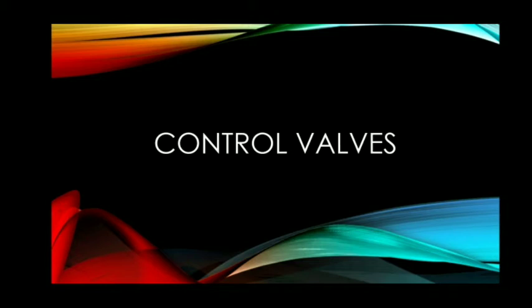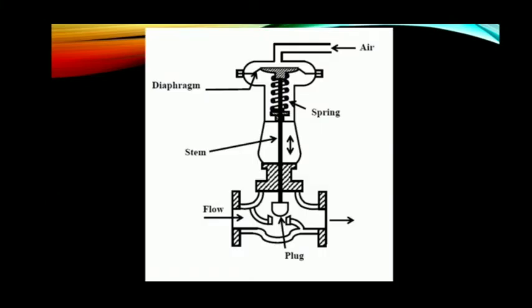The control action in any control loop system is executed by the final control element. The most common type of final control element used in chemical and other process control is the control valve. A control valve is normally driven by a diaphragm-type pneumatic actuator that throttles the flow of the manipulating variable for obtaining the desired control action.